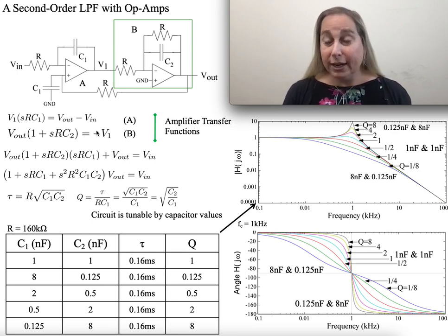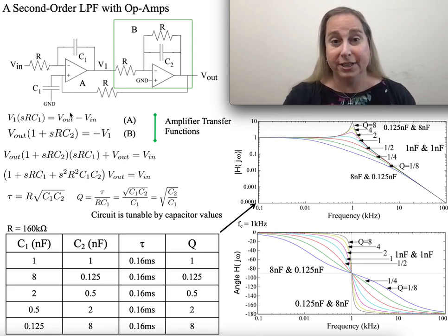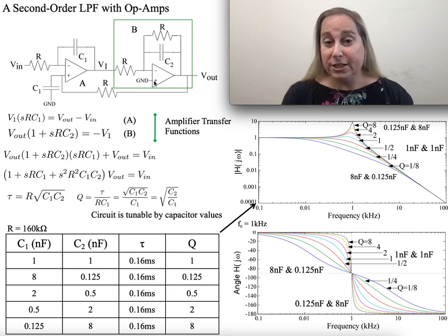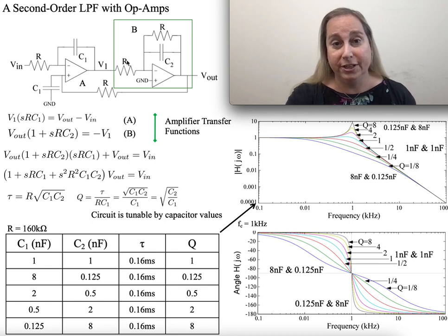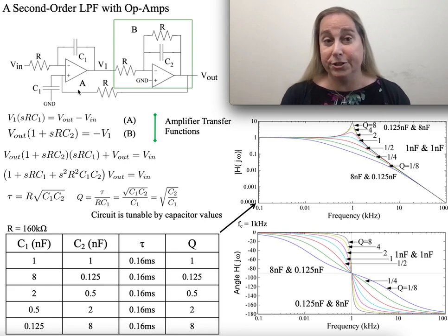By doing so, it actually allows you to get a little bit of different intuition of what's going on here. And unlike a transconductance amplifier version where I would change the bias currents of the amplifiers, here I just decided to change the capacitors. In fact, I decided to make one element basically a low-pass filter with a gain of 1, which is very similar to that initial stage. Of course, inverting gain.